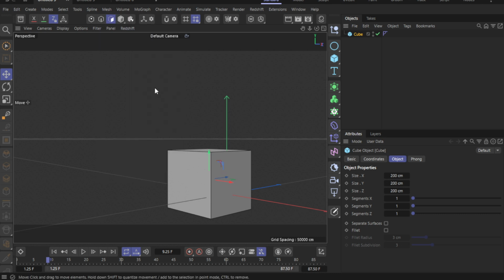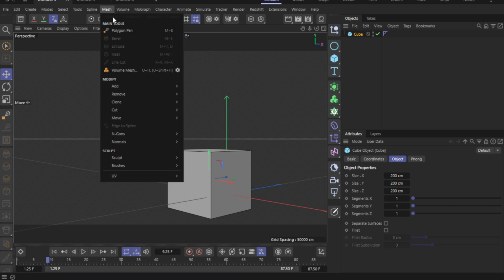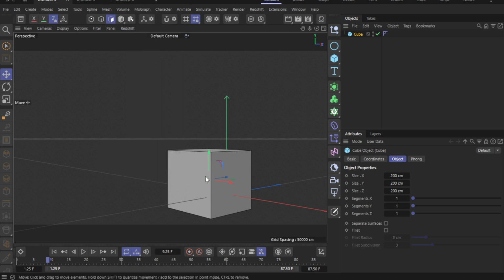here. Make sure your target object is still selected, and have the spline you want to use visible in the viewport. The spline acts as a guide for the cut, so position and scale it beforehand so that it aligns with the shape you want projected.